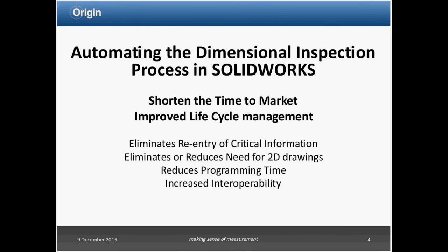Here's another one. Does Checkmate have the function of extracting features from a point cloud? Yep, we just talked about that. In the example shown, the original alignment was automatic. The point cloud from your laser scanner is going to be somewhere in outer space. There's an automatic alignment to the CAD model, so the initial color map you see is basically the point cloud aligned to the CAD model, and then you later go in and refine it to align it to whatever your ABC coordinate system is to get more accurate results.